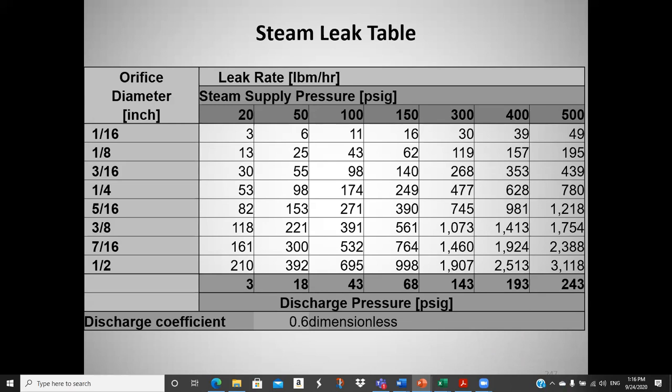So the only way we really have to do this is to go to a laboratory and make a bunch of orifice plates, or buy them, that have a 1/4 inch hole, 3/8 of an inch hole, 1/2 inch hole, 1/16 of an inch hole, whatever we got over here, and set those up in a highly instrumented system and measure the flow rate through them. Then we have some degree of confidence in this. The problem is when you go out in the field, your leak is not an orifice with a hole in it. So you have to somehow make a judgment call.